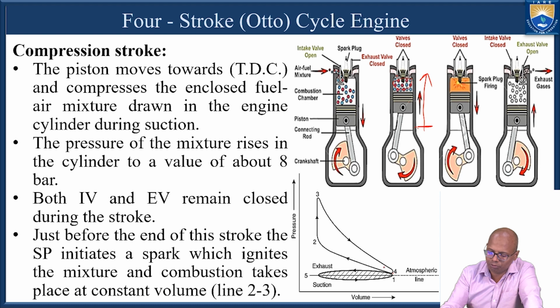So the line 1 to 2 represents the compression stroke, where the pressure increases, and in 2 to 3, because of the combustion, the pressure further increases.